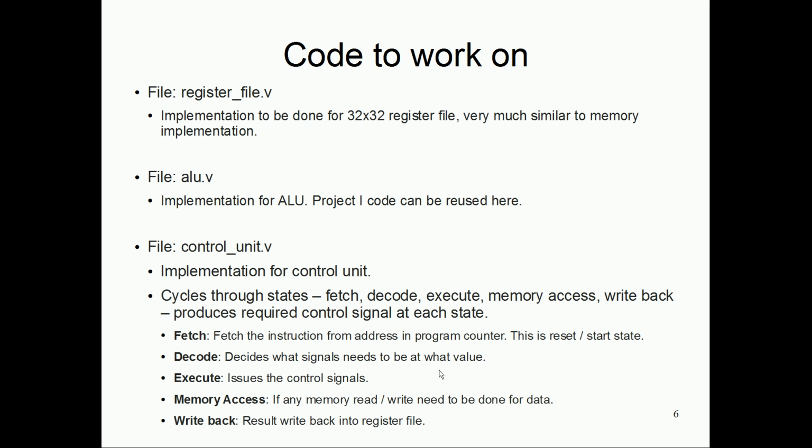Also, we are reading the register file, so we issue the register signals: register read, write, read address, write address, whatever needs to be done, and get the data back in the controller. And execute is basically where you're controlling the execution of the ALU. You are setting the operation, plus, minus, division, multiplication, whatever, those 7 or 8 functions we defined there, setting the operands and taking the result out of that.